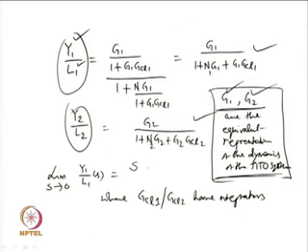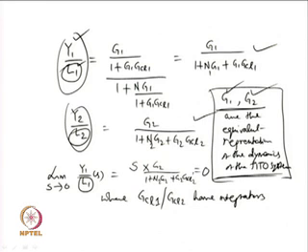So, ultimately it will be s times G2/(1 + N2 G2 + G2 G_CL2'). When s tends to 0, the whole term becomes 0, and that is how the effects of the load disturbances L1 and L2 are nullified in the output of the system. So, the limit cycle experiment or the relay feedback experiment will not be disturbed by the presence of static load disturbances. This is the major benefit you get from the online identification scheme.